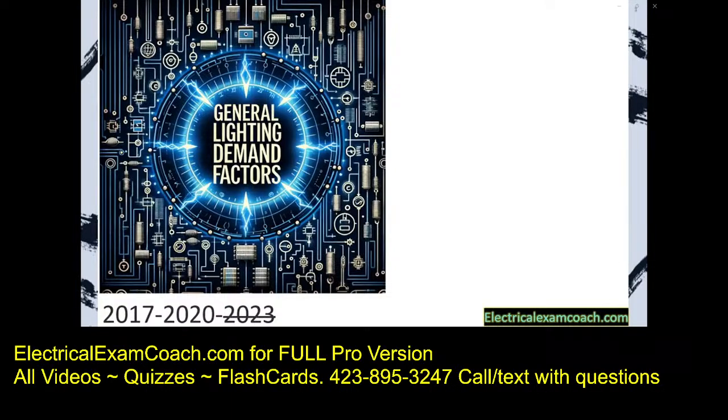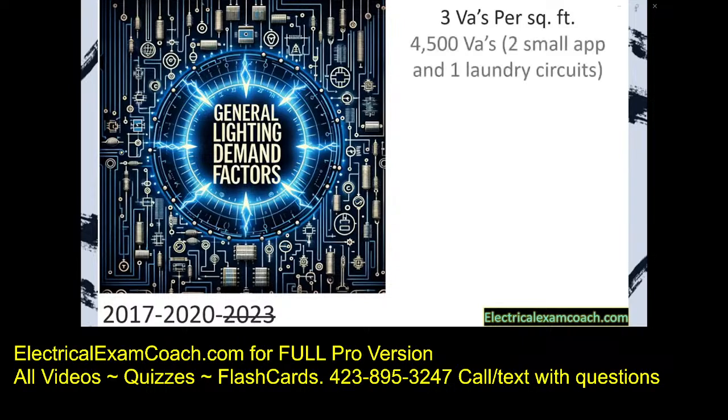Hey everyone, welcome back. I am the Electrical Code Coach from electricalexamcoach.com, and this is lesson 4.2 in our video series. Now we're going to learn how to apply the demand factor to the general lighting load. At the beginning of the program, we learned that it was 3 VAs per square foot, and we had to add on the 4,500 VAs for our 2 small appliance and 1 laundry circuit.